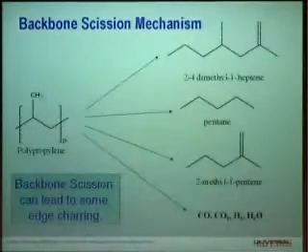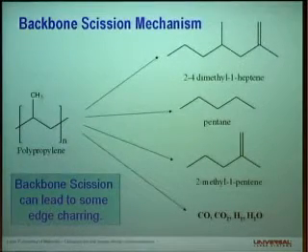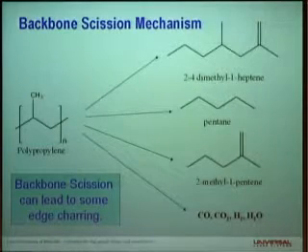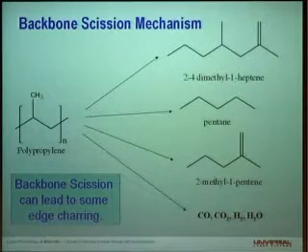But in the heat-affected zone, you're going to have complexes of these chains, some of which aren't going to be volatile. They're going to have more heat applied to them because they're in the heat-affected zone. They can fold back on themselves and recombine. They can create double bonds. They can cross-link to other similar polymers. And the result, in general, under the influence of heat and generally not enough oxygen for complete combustion, is you concentrate carbon right along that cut edge. And that concentration of carbon is what we commonly refer to as charring.